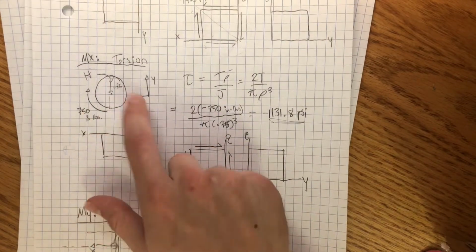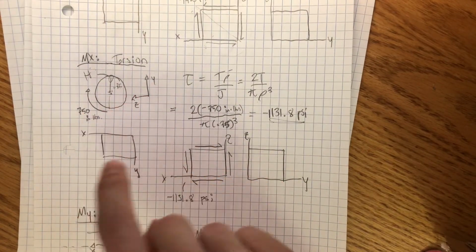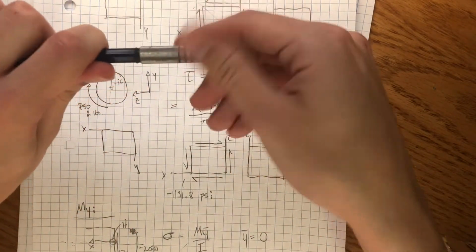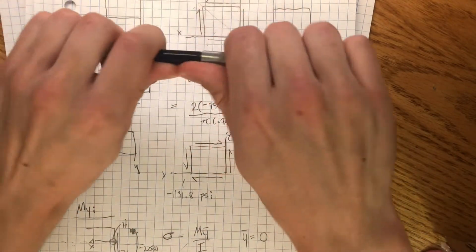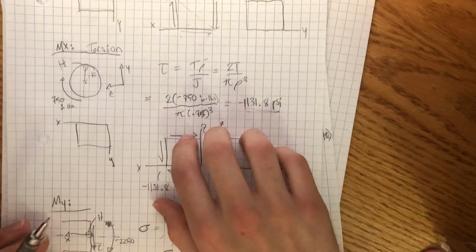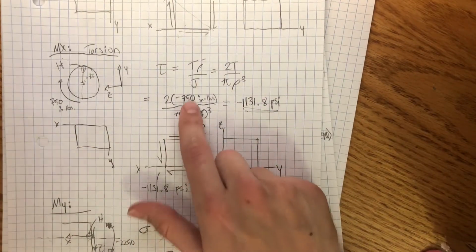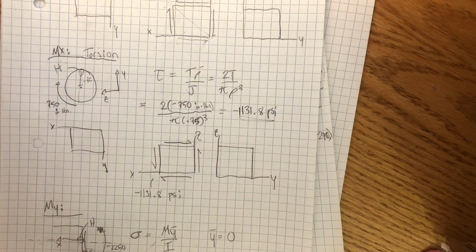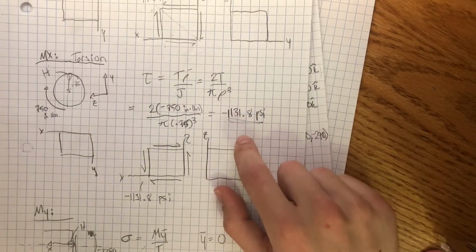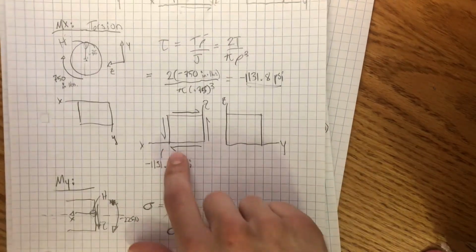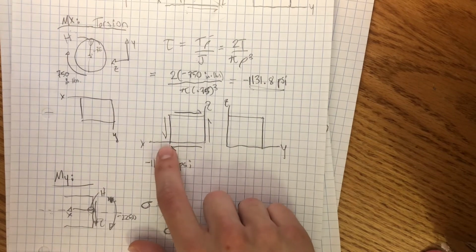And because the moment about the x-axis is going to twist, right? It's going to twist like that, as opposed to bend like that, we know that it's not going to create any force of tension or compression. It's going to create a shear force. So we use this formula, torque times rho over polar moment of inertia, and that's how we found this value here. And as you can see, it is also on the xz plane, but it is negative.